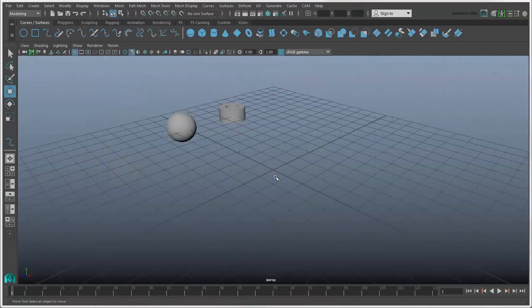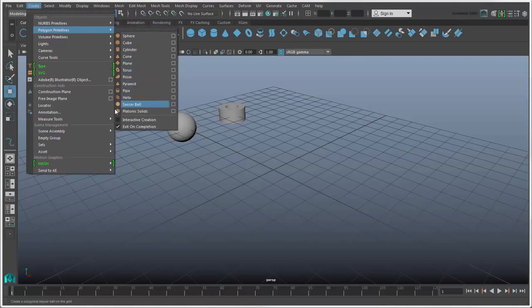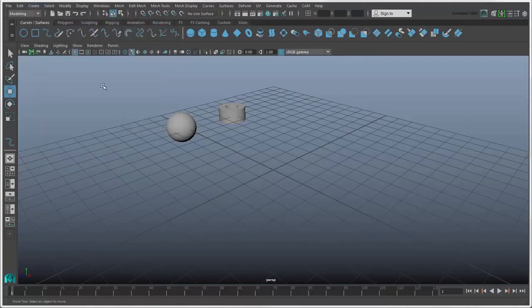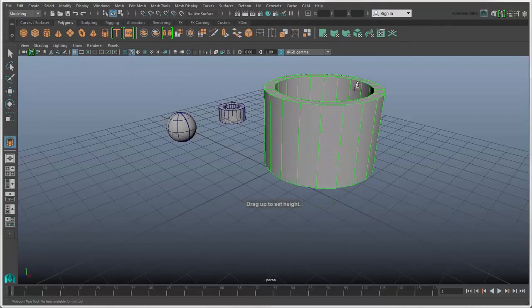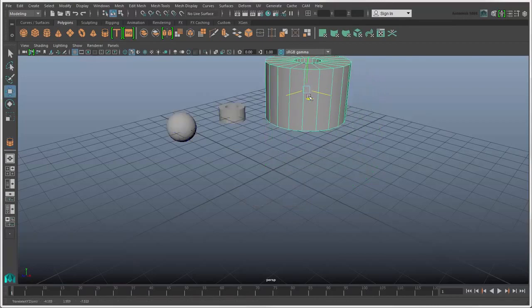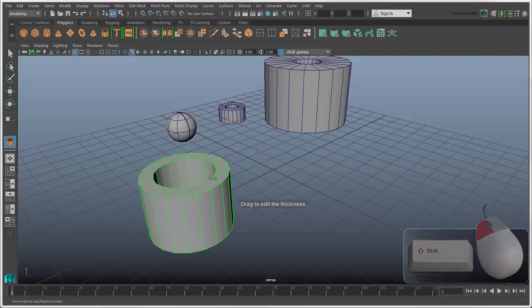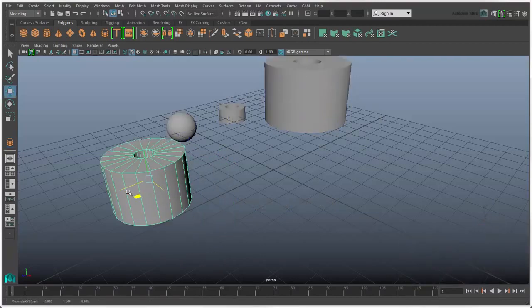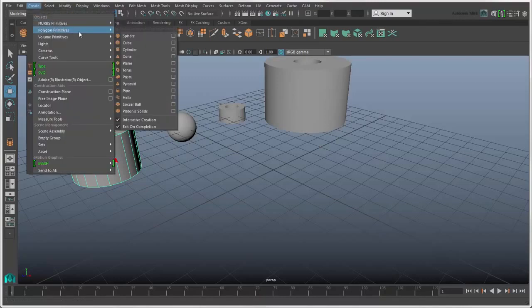If you want to make a custom-size primitive object, turn on Interactive Creation in the Create Primitives menu. And draw the primitive in the scene wherever you want it and to whatever size you like. You can also press Shift while dragging to grow the object from its base, which keeps it on the grid. Let's go back to the default mode with no interactive drawing.